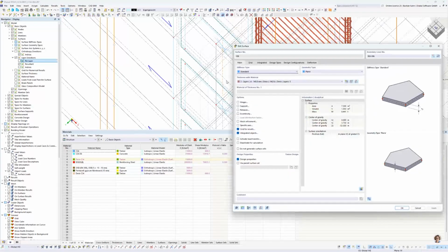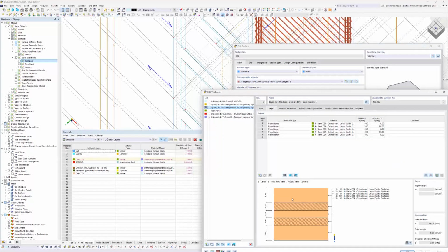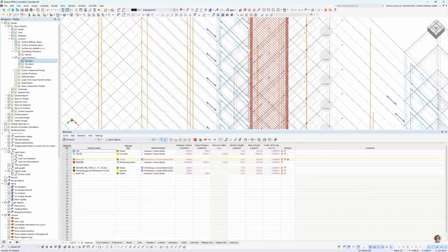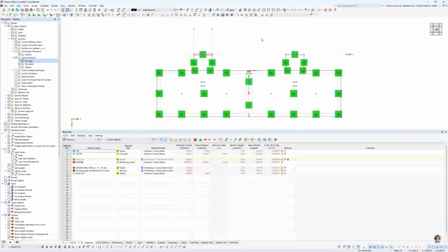So when we look for these ones, you see there are top and bottom layers with 40 millimeters in thickness. And if we span the CLT plate in this direction, you would have an enormous settling in the structure, which is something similar to what you have when you are modeling a log home, like 20, 30 centimeters or more in such a high building. So that's not what you want. And we have to change it.